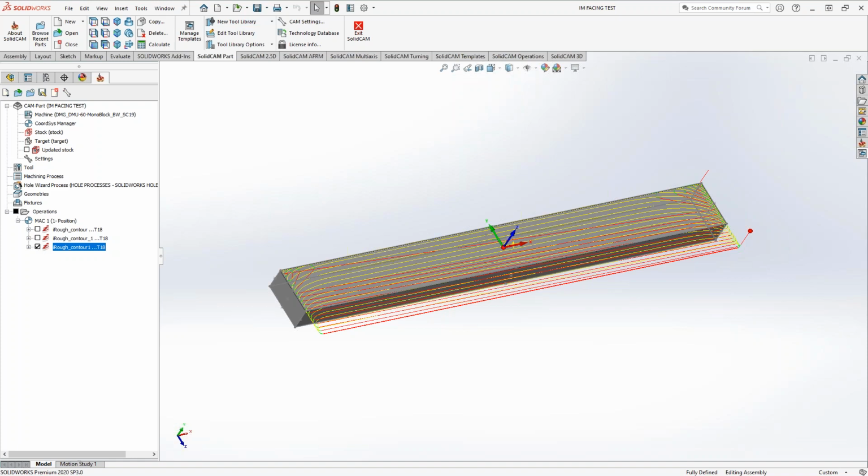And the reason why we're getting this path this way and not getting the island separation in there is because we told it, we're basically forcing its hand. So we can manipulate the path in iMachining even with the algorithm turned on, but this way is going to take a little bit more work on your end, and you'll have a little bit longer cycle time, but your tool life would still be just as good as our first one. You just have a more efficient path, because if you count up each one of these lines going along here, each has a full retract over.